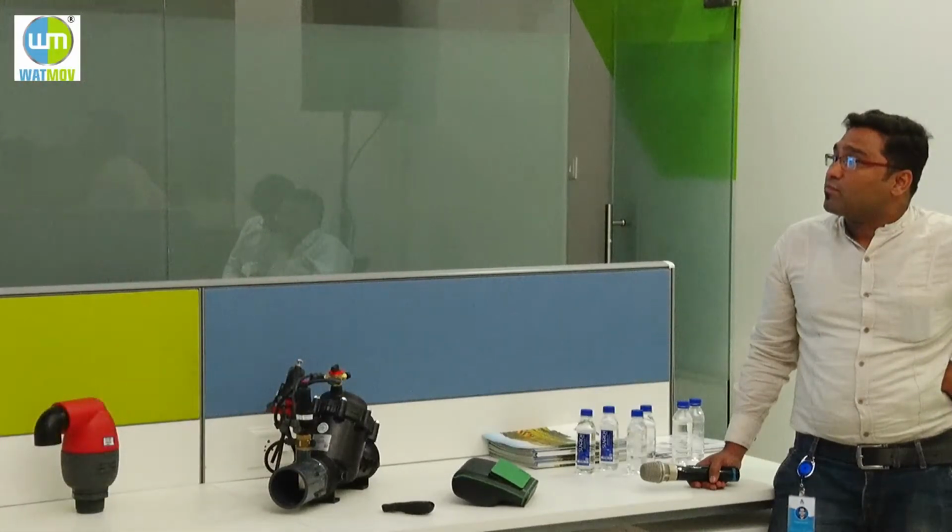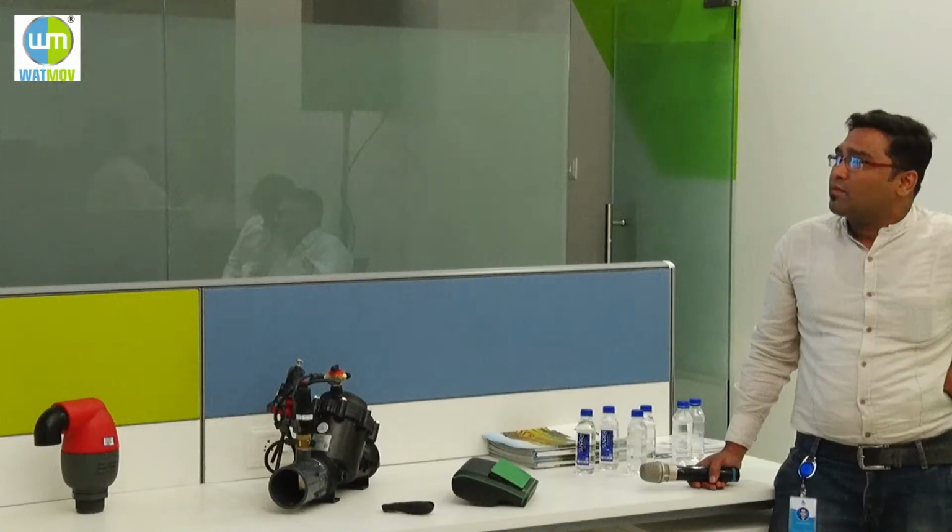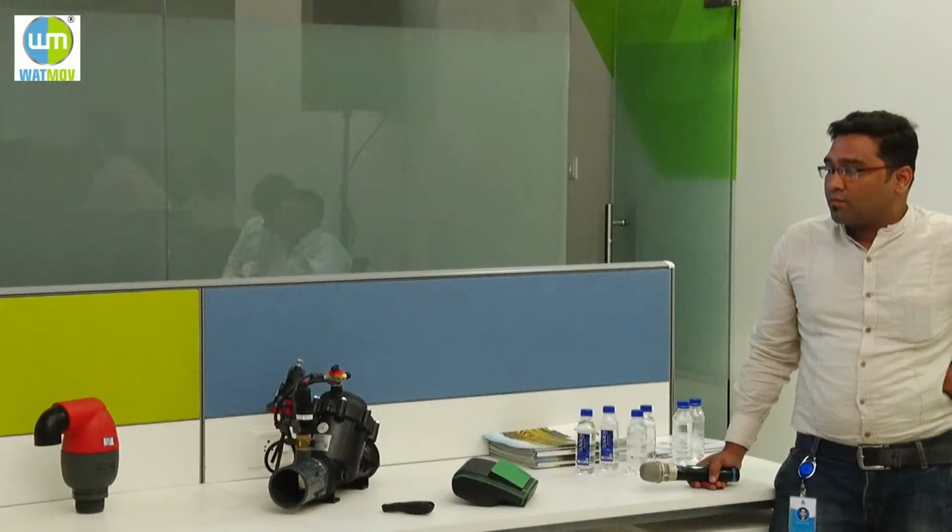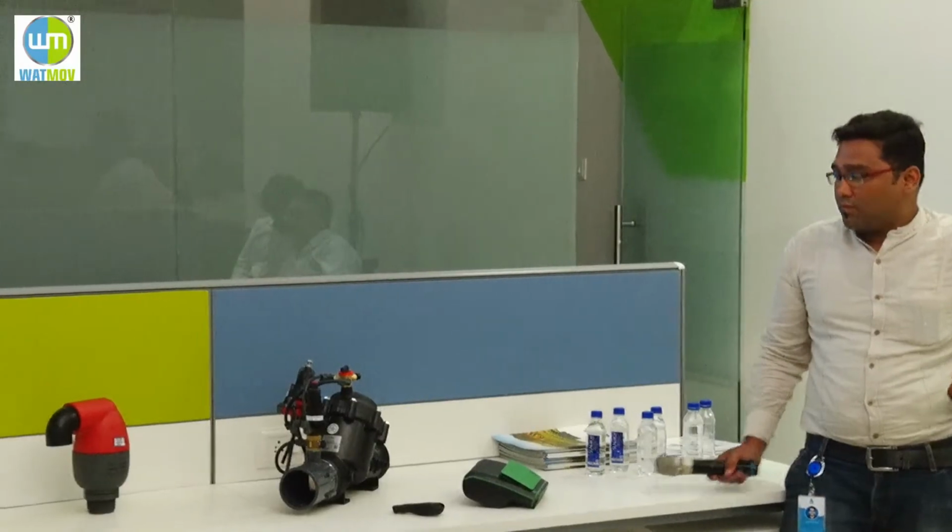Another thing, the orifice is custom made per your project, per your flow setting. And if you want to change the calibration, it's very limited. You probably will need to change the entire orifice size. Here, you can change and adjust the calibration on site by using the calibration bolt. So this is important. And of course, when the valve is not limiting the flow and not reducing the pressure, it's fully open, transferring the pressure that you have and the flow that you have. Continue.